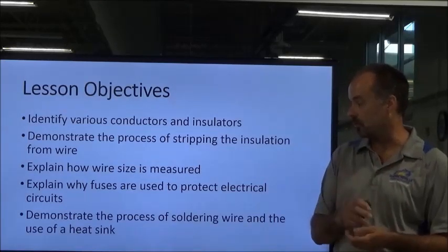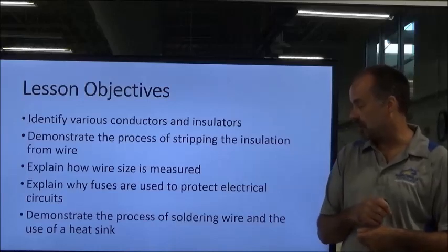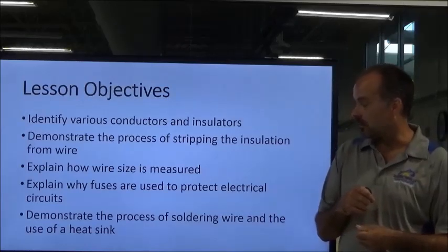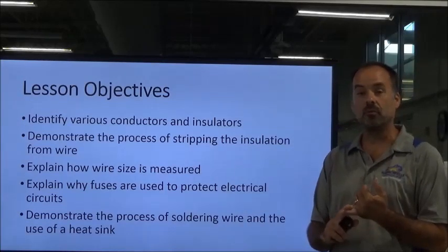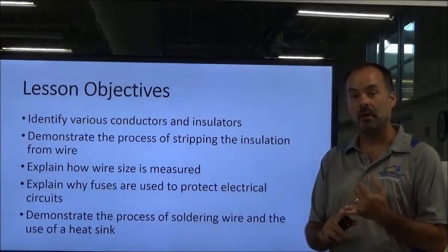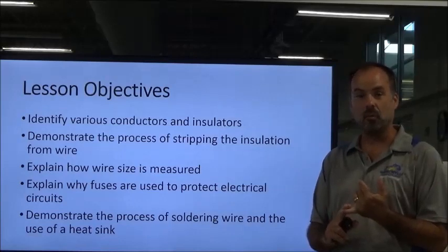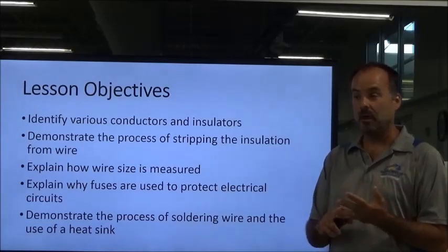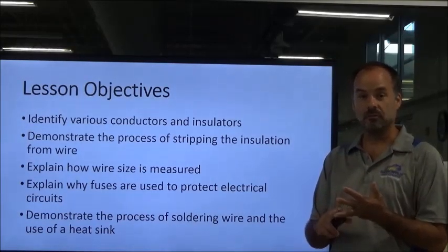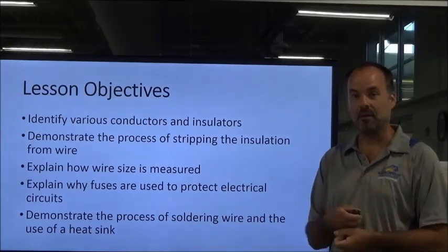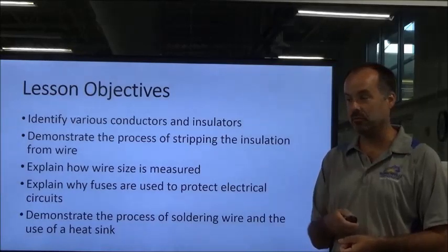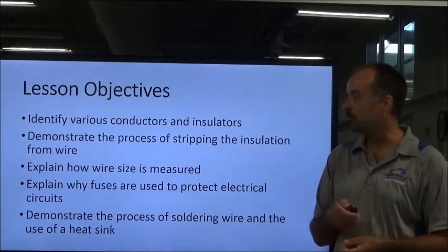And then the last thing we're going to cover is demonstrate the process of soldering the wire and the use of a heat sink. So this is one thing you're going to be doing when you come to the lab. You're going to be creating splices in wire using various methods. You're going to be gauging the wire size and being able to identify a given wire size using a tool to be able to gauge the wire.